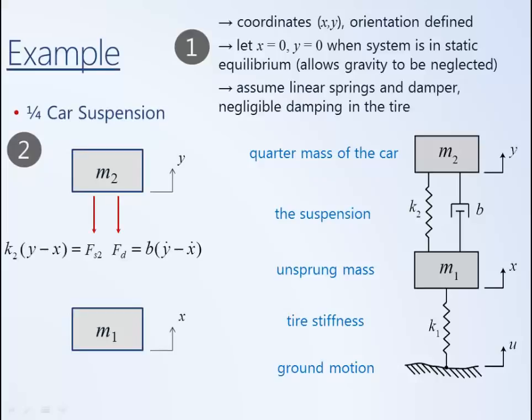That is, imagine that M2 is fixed, move M1 in the direction of the positive coordinate, which is up, and imagine whether or not the spring is compressed or stretched, and what the direction of the generated force will be. An alternative is to just point the forces to be equal and opposite of the ones applied to mass 2.